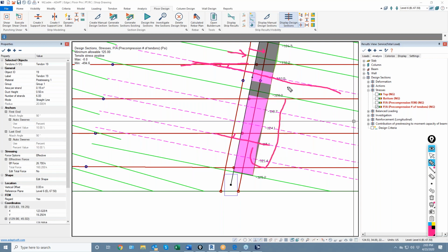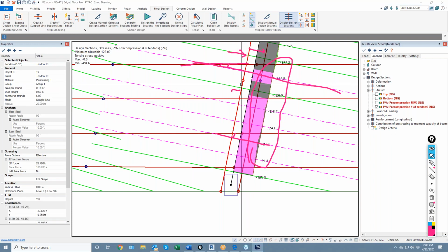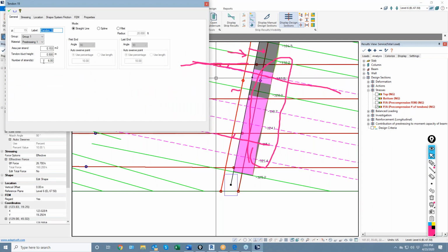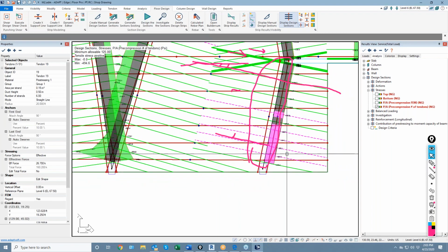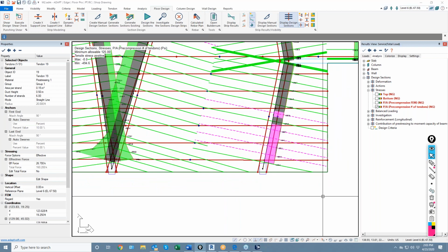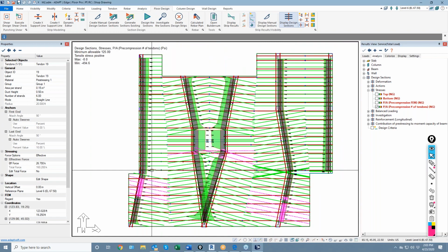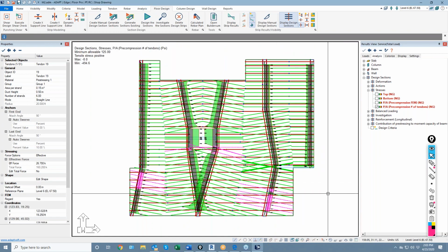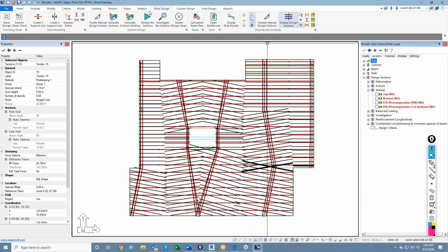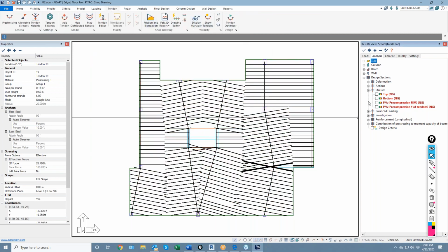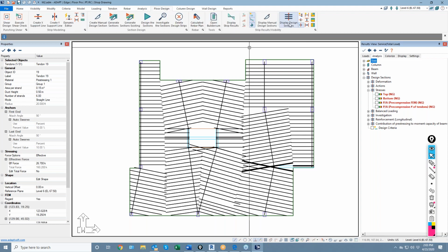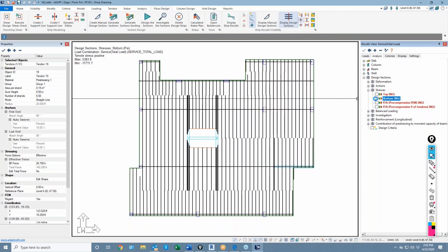But here you can see we're a little bit low on this line. So we might add another tendon here. I don't know how many tendons are there now. There's 6 times 2, so we might change this one to 7, have a total of 13, reanalyze, redesign to update that location. The same thing is going on here, and there's a little drop there. The second thing we might want to check after we solve the pre-compression would be the stresses. And if we go back and say, okay, let's go back to the X direction. I think it's a little easier to see that.